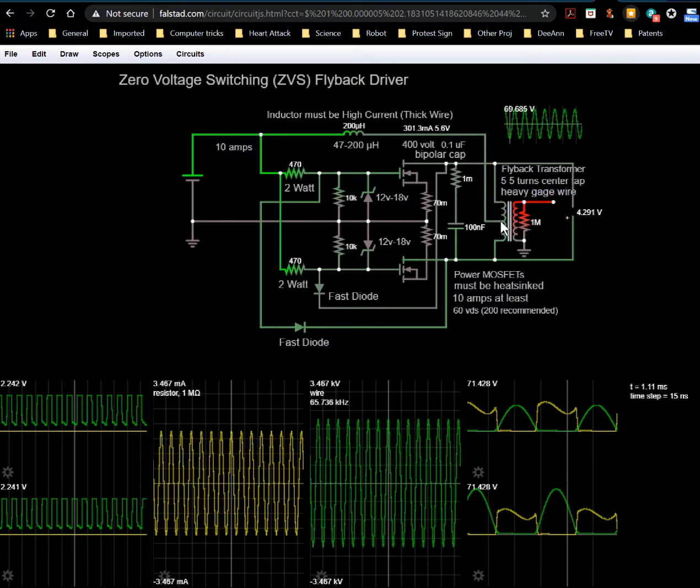So that's one of the reasons you can actually get 2 or more times the voltage across it, because this doubles. And two, if you realize that this is like a DC pulse you're putting into it, you can think of it as, well, if you're converting DC to AC, you've got to multiply it by 1.414 to find the peak from the average DC value. You can sort of think of this like that, that it's converting an average to an AC value. So you can think of it as being like 1.4 times the peak voltage here, which is double the applied voltage.